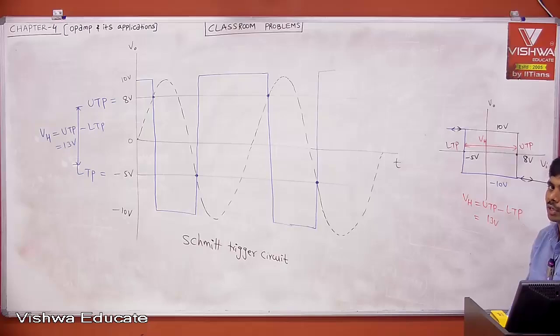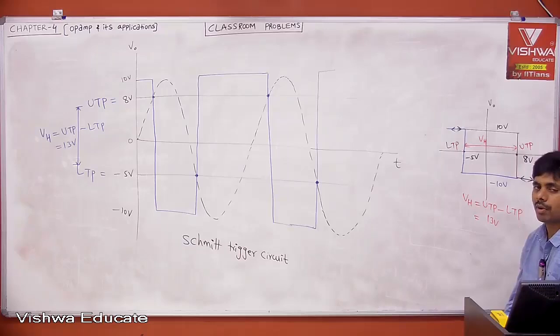Along with storage and transfer. We cannot store analog signals, we can store but with huge power. We have analog oscilloscopes, but we need to have power continuously, then it will store the analog signals, but it is power hungry and we cannot transfer analog signals unlike digital signals, because we don't have detection and correction in case of analog, but in digital we have detection and correction. Therefore, storage and transfer, digital data transfer, with error detection and correction, is mainly the advantage of digital, and people went to signal processing, digital signal processing also in the digital domain.